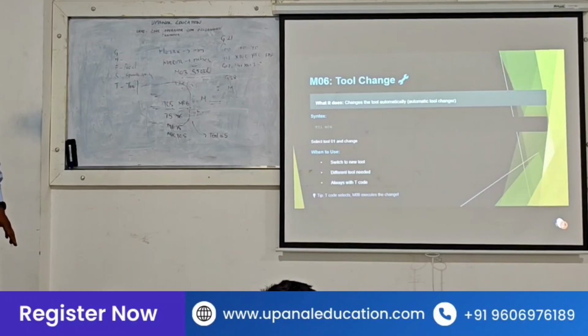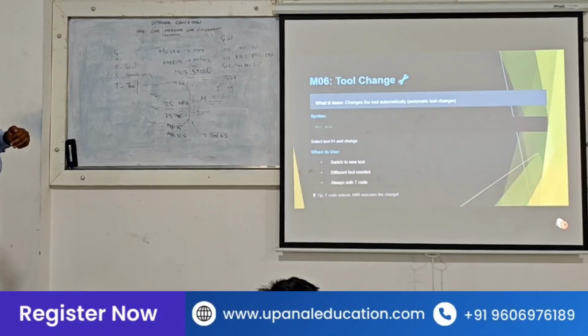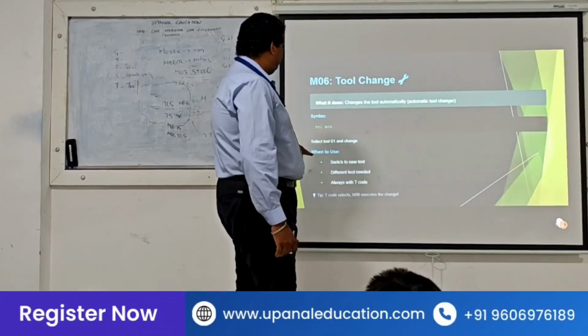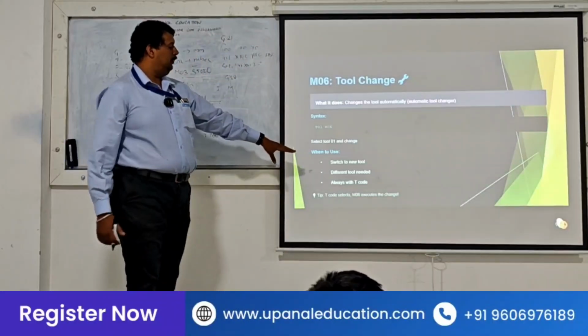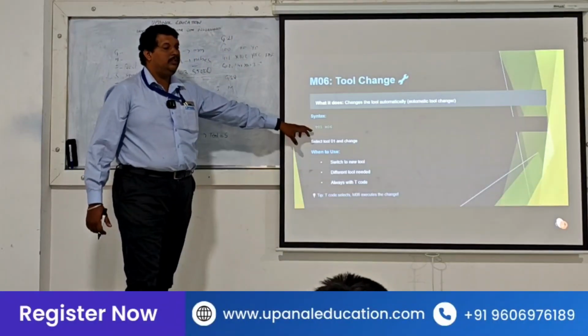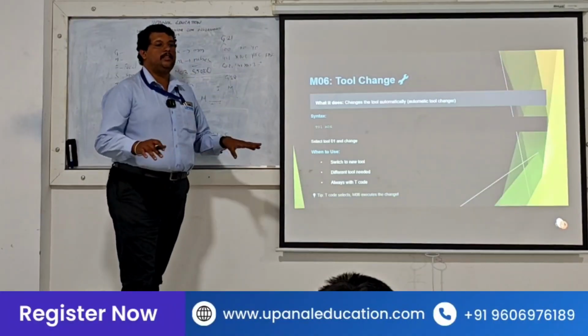Always capital letters. That will show in the machine. So we use it for changing to a new tool when we need a different tool, and I told you it will always be with the T code. Just giving M6, will it work?